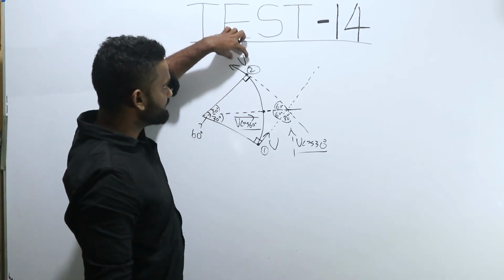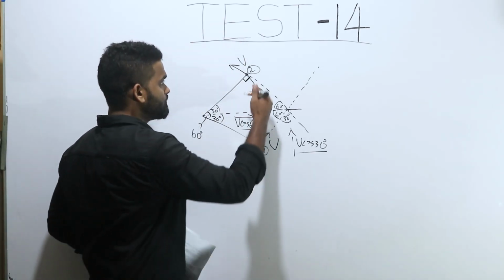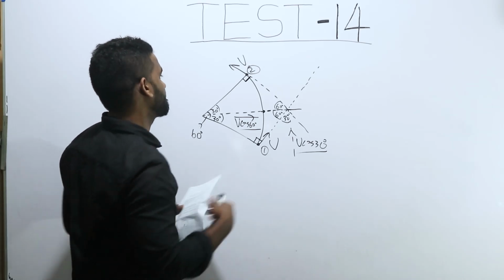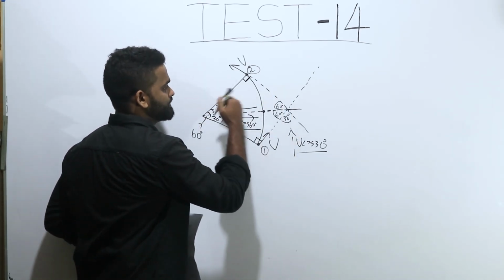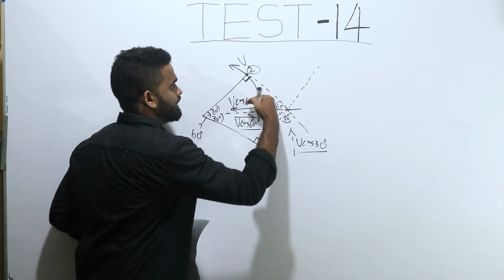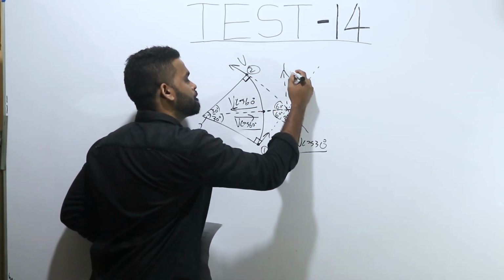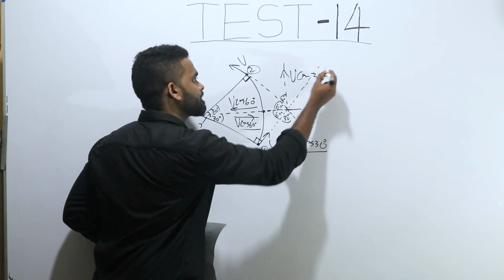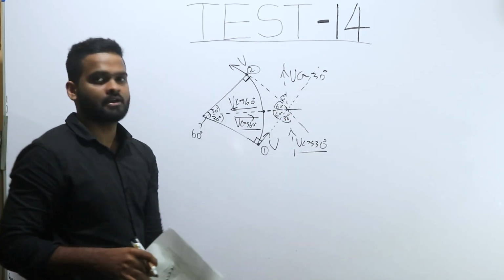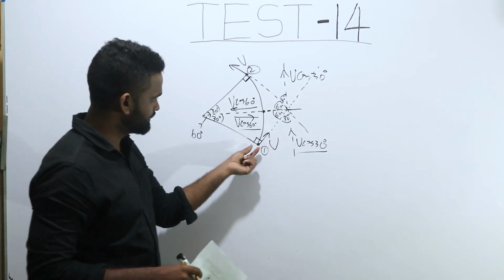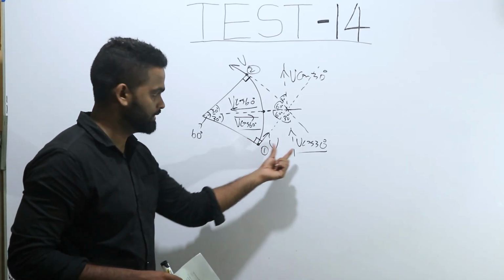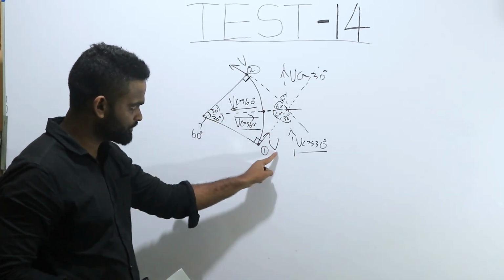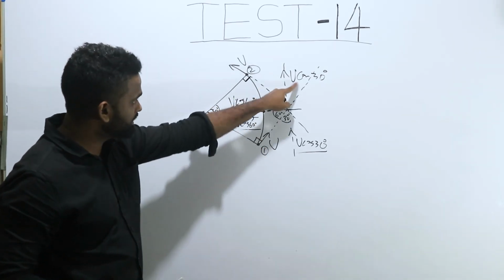So these are the components of this V. Then I will resolve this velocity onto this line. V cos 60. You can see its direction is to this side. V cos 60. To the normal direction, V sin 60, or it could be V cos 30. Okay, so I just resolved both velocities. Those are the components of this velocity, and these two are the components of this velocity.